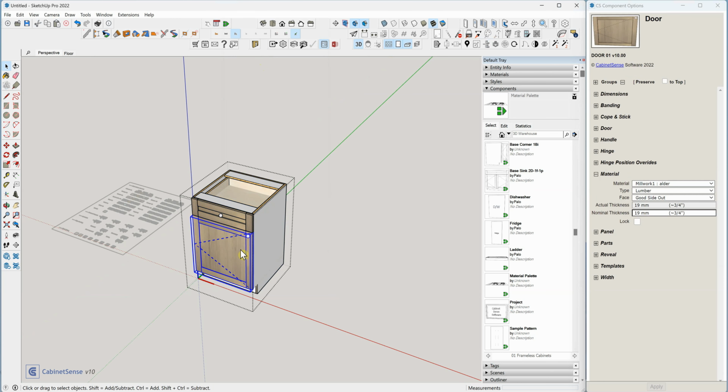So for example, we have a drawer box bottom, 1/4 inch. And if I click on it, can't really see it because the bottom is really dadoed into the sides and we're not seeing any of the highlighted edges. Turn on X-ray mode, and there they are.